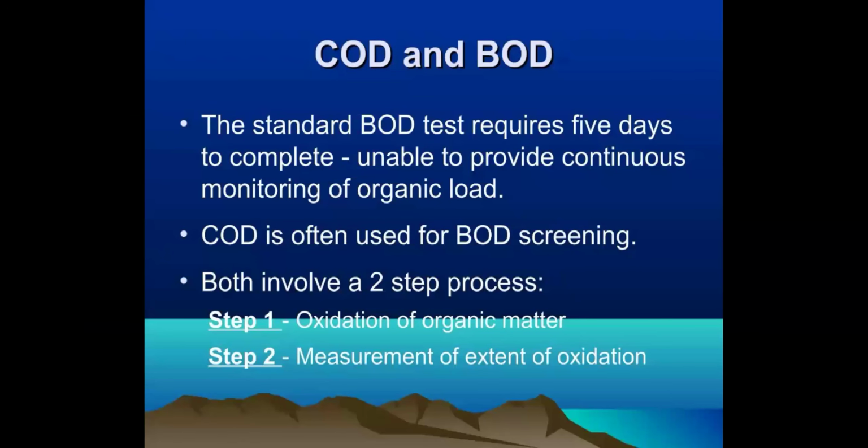The standard BOD test requires 5 days to complete, so it is unable to provide continuous monitoring of organic load. COD is used for screening. Both involve a two-step process. Step 1, oxidation of organic matter. Step 2, measurement of the extent of oxidation.